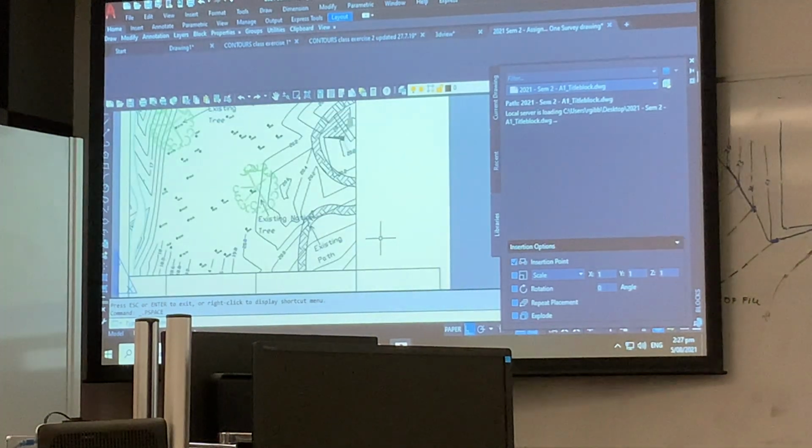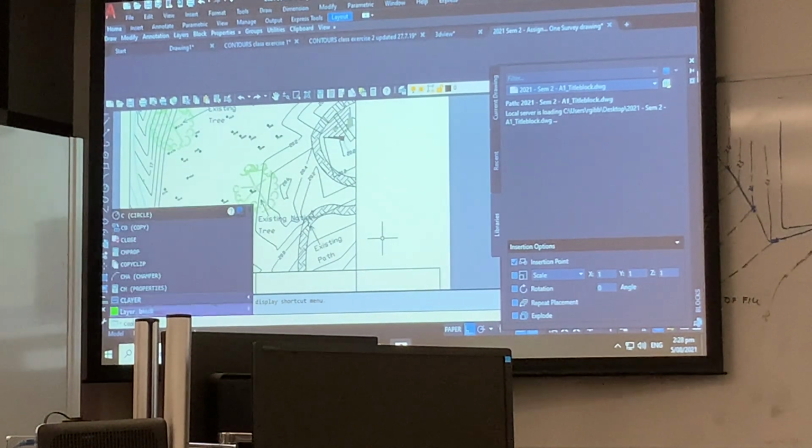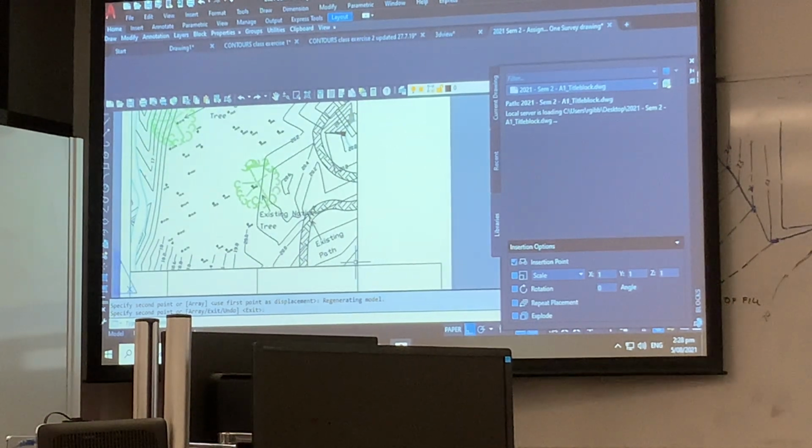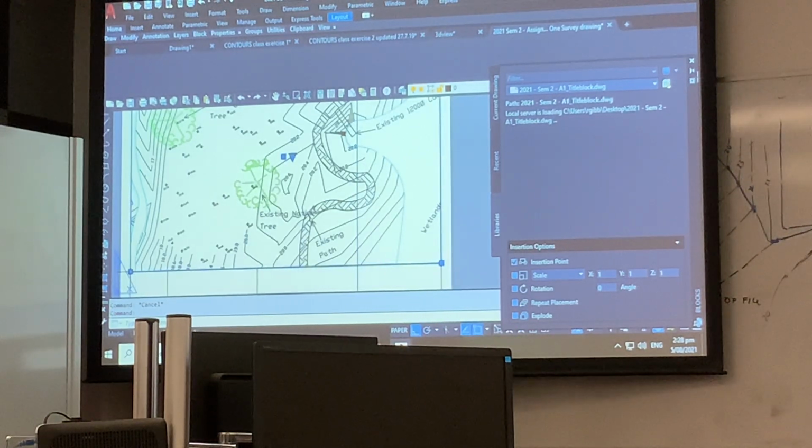Now, the next step in this is we go copy that from that point on top of itself. Enter. So we've got two viewports, one on top of the other. The top one, we stretch it from there to there, and we click on it again, and we stretch that from there to there. So now we've got two viewports, that one and that one. They should be the same scale, 10 XP, because they should be, but it doesn't hurt to go List.